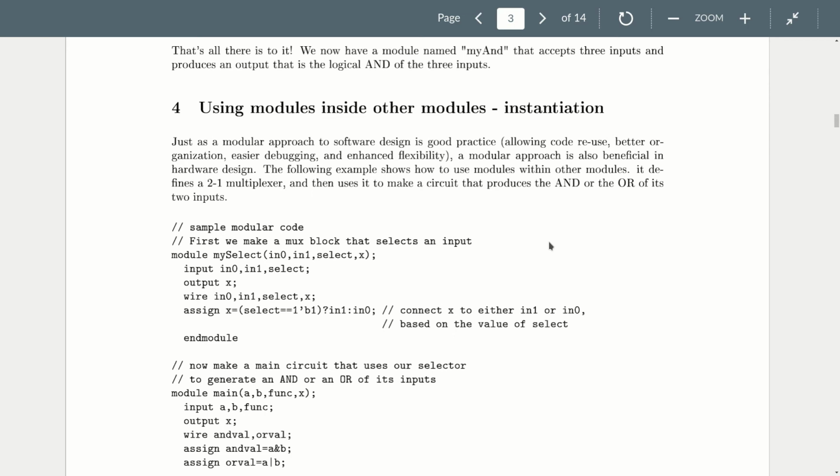Now that's still kind of descriptive Verilog. That's describing your circuit. And there's times when that's what you want to do, as opposed to trying to describe the behavior of your circuit. But maybe it's a combination, right? Maybe I'm describing the behavior of this arithmetic unit, this thing that can add or subtract or do logical operations. But now I want to connect that to some other piece of circuit in a particular way. And it might use a description of the circuitry like that. So that's what this section on instantiation is. And basically,